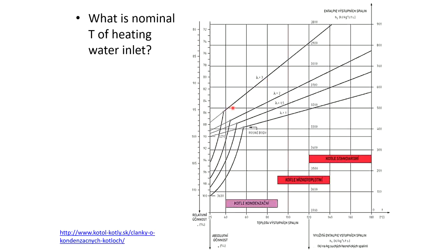So when we cool down the flue gas to the same temperature, let's say 60 degrees C, we would have higher stack loss, so we would have lower efficiency over here than if we have the oxygen excess just 1, and we would have higher efficiency over here. Now, if the lines would be just straight, it would mean the water would not condense, but beyond or below the dew point, the water would condense.